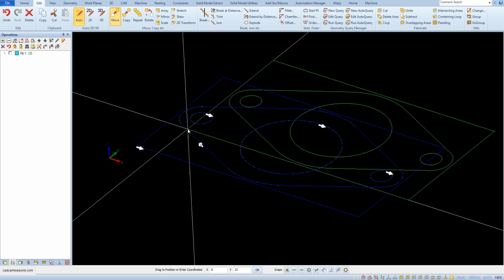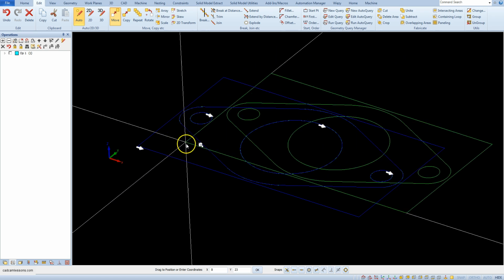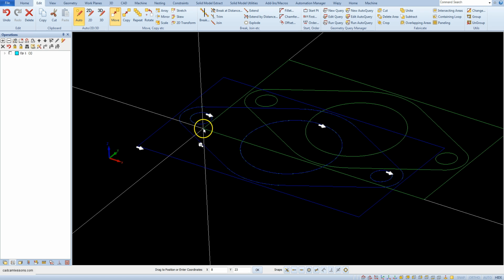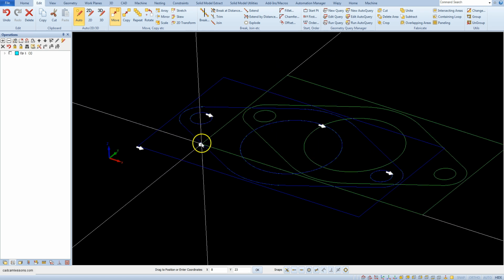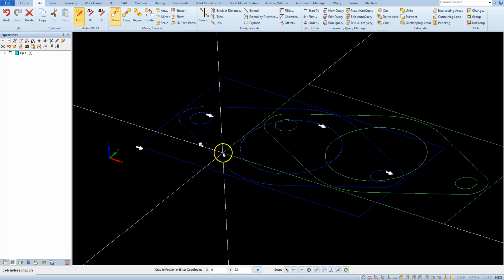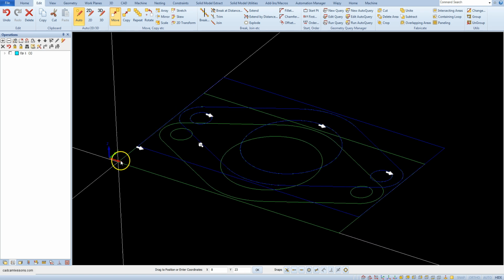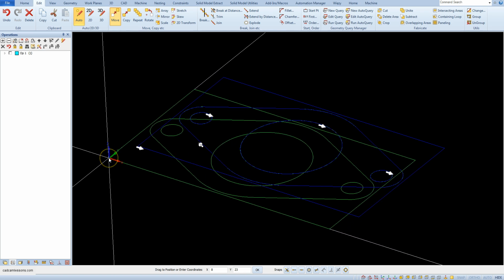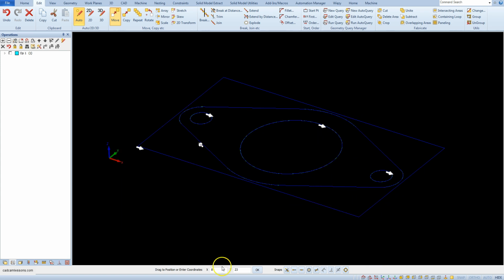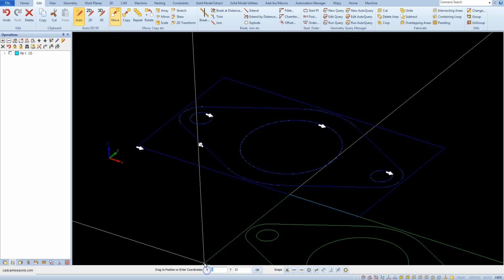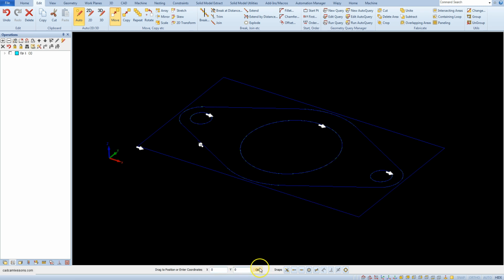As you can see, as well as when moving the geometry in the working area, all are attached to the base point. Now we have to determine the place where we will move this point. As you can guess, we want to move this point to the coordinates x0, y0. Enter these coordinates on the command line and click OK.